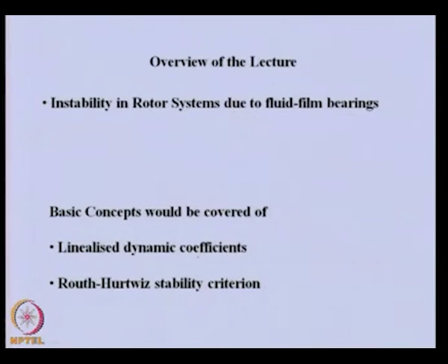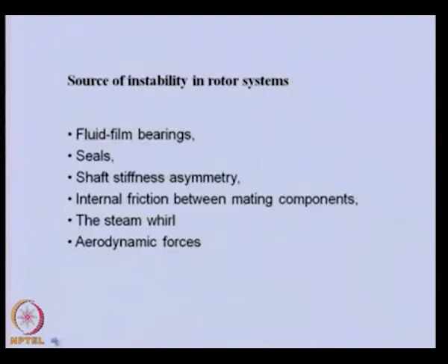Before going into the stability aspect of the fluid film bearing, let us see what the various sources of instability in a rotor bearing system are. The most common is the fluid film bearing. We know that in forced vibration the most common force is the unbalanced force, and in instability the most common source is the fluid film bearings.